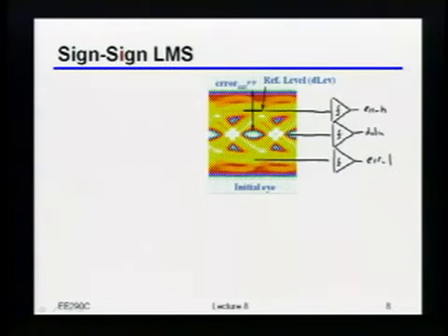There are things that are called sign-magnitude LMS, where one of the things that you deal with is sign, meaning only 1 bit, and the other one is analog. There's the reverse, which is, I think, sign regressor or something like that, which means that the other thing is analog and one of them is sign. And then finally, sign-sign is just the lazy man's version, which of course is what we're going to be doing here, which is just you do 1-bit estimates of everything.